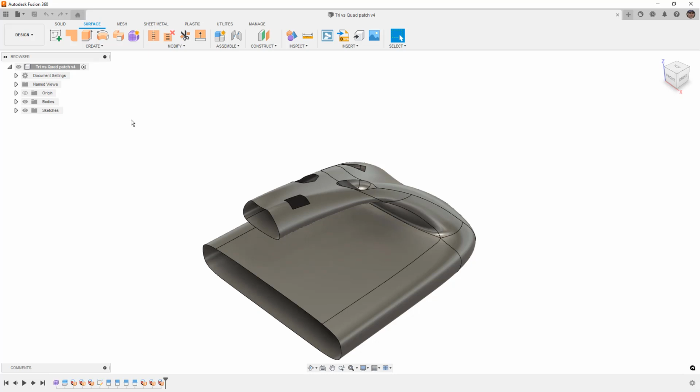Now, there are some, like SolidWorks, which I have to mention here, where you have tools like boundary fill and loft and sweep, and you have their patch tool, which can essentially overlap and do the same thing in a lot of cases. Their version of the patch tool allows you to have sort of an open section, an open selection, where Fusion, it has to be completely closed. All the edges need to touch.